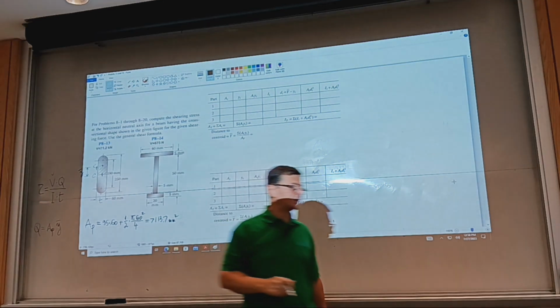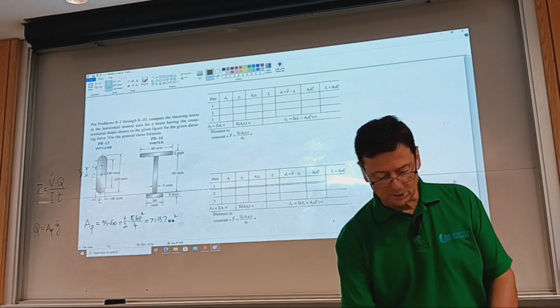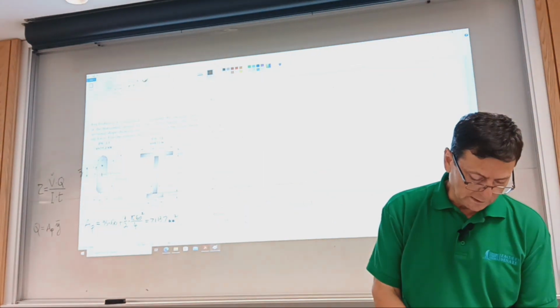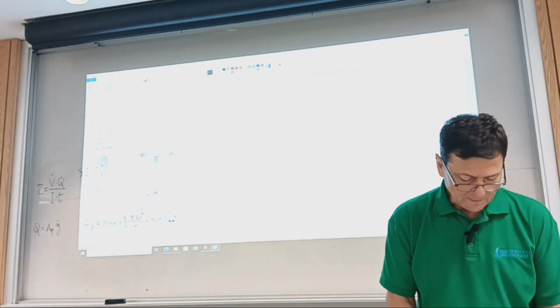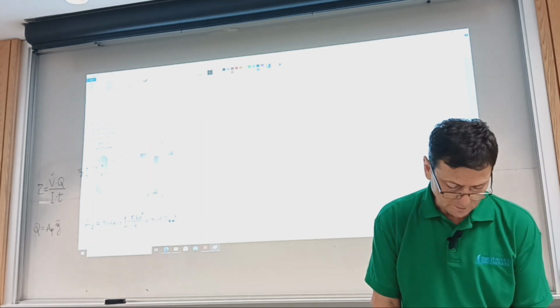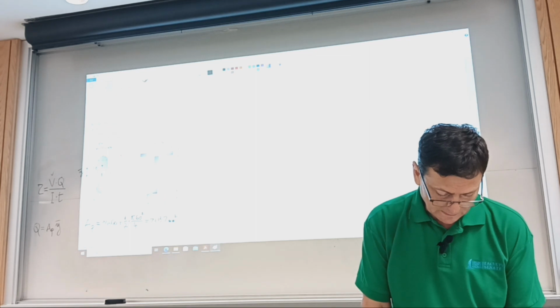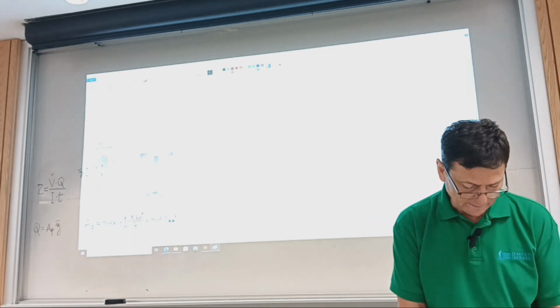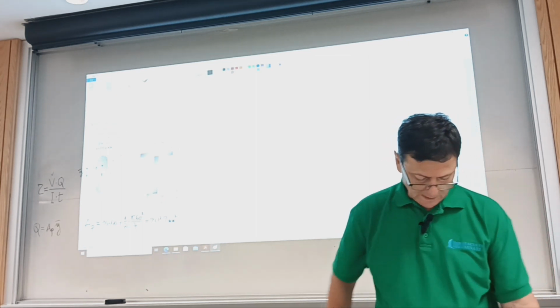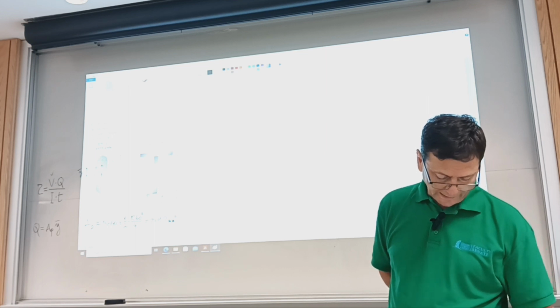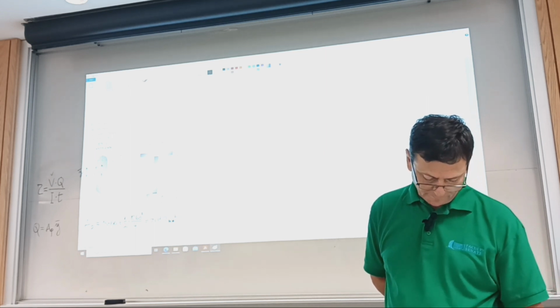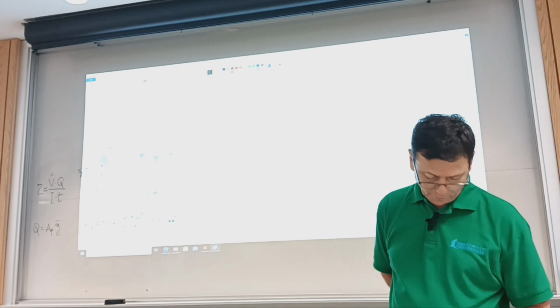And for a rectangle, the area moment of inertia is in the back of the book, appendix 1. I used to have it memorized, but I no longer rely on my memory for certain things, and I know they are written down. So we're going to use Ix on page 753. So it's BH to the power 3 over 12.